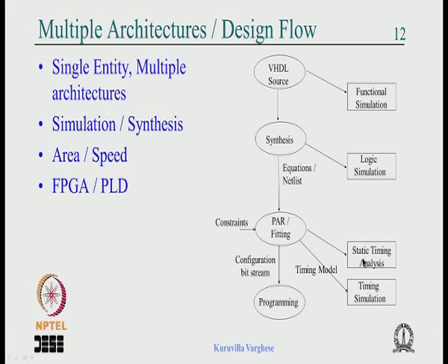But static timing analysis is a very quick analysis. Suppose you have a register to register path, it is not that you give clock, reset and input and try to check the output waveform. Instead, all the delays from the source register to the destination register are added together and reported. So it is very fast, but the real problem with static timing analysis is that it need not be accurate, because in a complex circuit there are a lot of paths. There may be, say, 6 source registers and 12 destination registers, and some of the paths may not be active at all in real life.